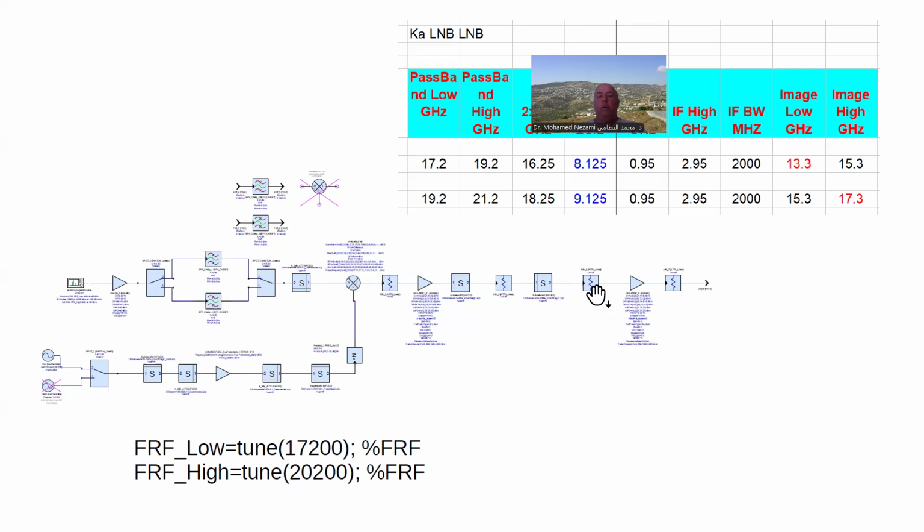And then I distributed about 4 total bipad attenuators. These I throw in everywhere so that I get good isolation and sacrifice a little bit of gain, but they make the design easy. These bipad attenuators are made of discrete 0402 resistors, while this one in here, because it's K band, is a professional MMIC chip attenuator absorber.